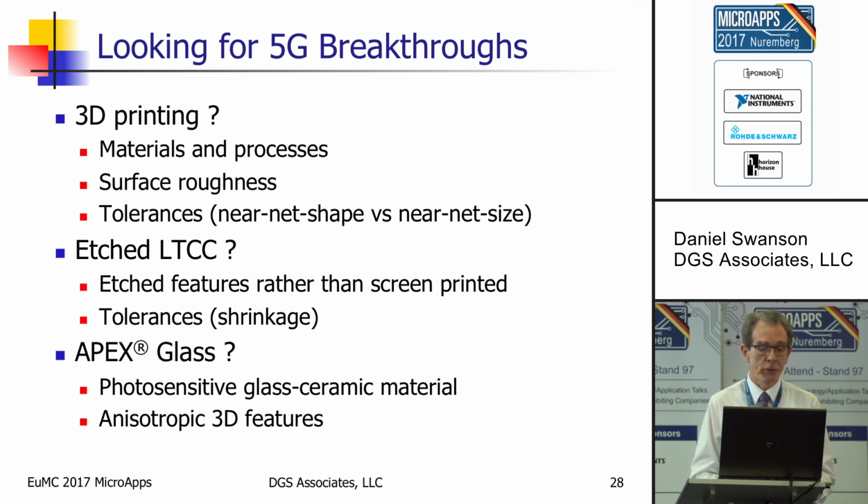What about LTCC? That's been around for a long time. Well, the new thing there is people are starting to etch circuits in LTCC. Normally, the conductors would be screen printed, and that's fairly low resolution. But I know of several people now that somehow screen print or deposit the metallization and then etch it rather than trying to use a screen.